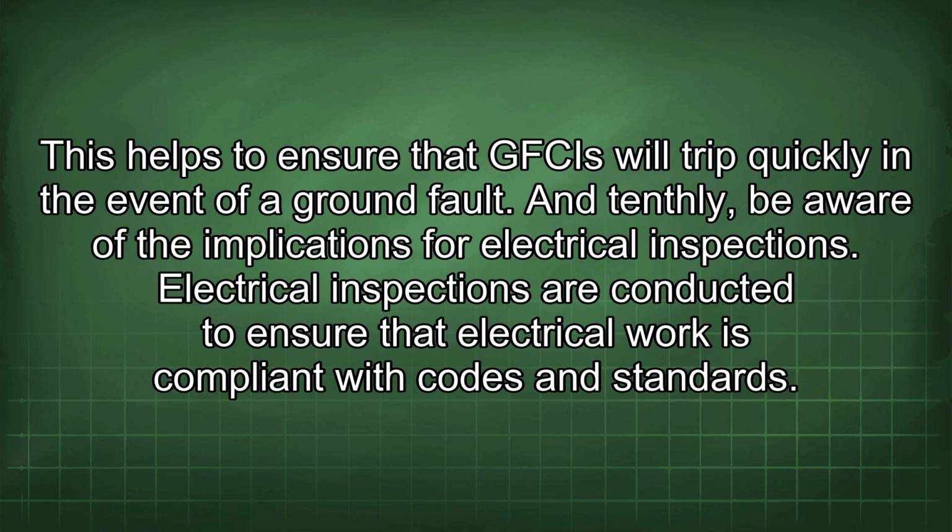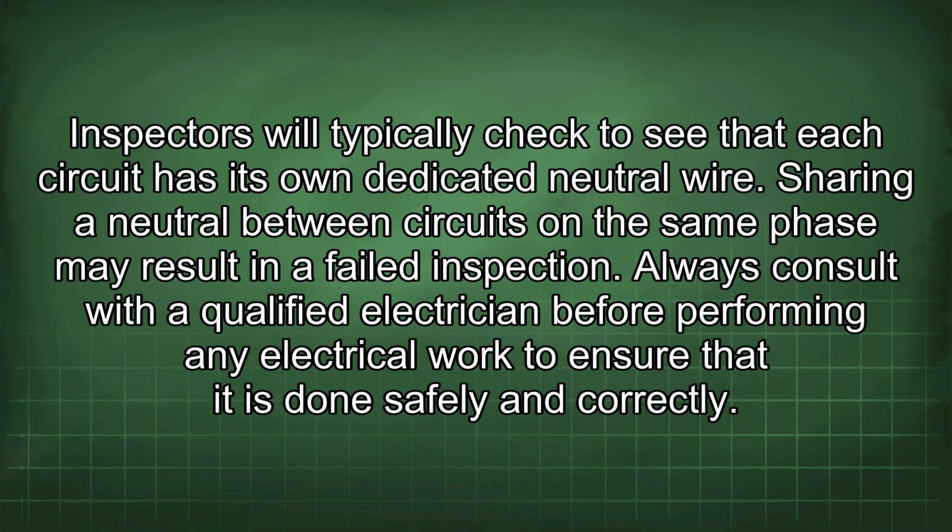And tenthly, be aware of the implications for electrical inspections. Electrical inspections are conducted to ensure that electrical work is compliant with codes and standards. Inspectors will typically check to see that each circuit has its own dedicated neutral wire. Sharing a neutral between circuits in the same phase may result in a failed inspection.